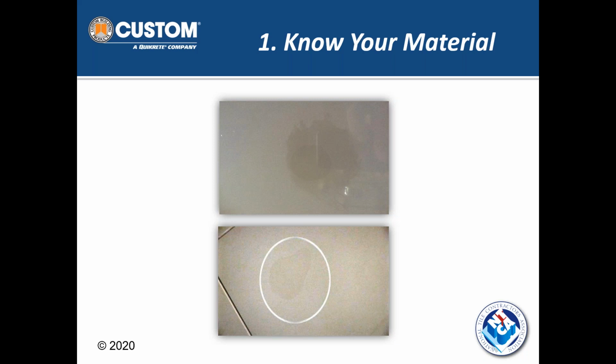If you look back at that chart, with granite and marble you're talking about an ASTM definition of 0.2 or 0.3% for granite or marble. Here we're talking 0.2% for this tile, and most people would say, well, sure, you need to seal marble. Well, this porcelain tile is in the same technical range in terms of absorption as the granite and marble.